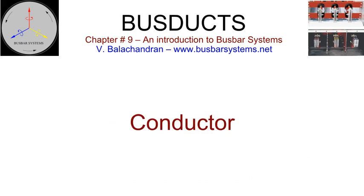In general, conductors with a rectangular cross-section, large width to thickness ratio, and in the vertical orientation make the rectangular bus ducts efficient and compact. This is adopted by most of the manufacturers of low-voltage bus duct. For low-voltage bus duct with copper or aluminium conductor, it is prudent to use a single bar per phase up to its maximum current rating, with the same size for the neutral bar.